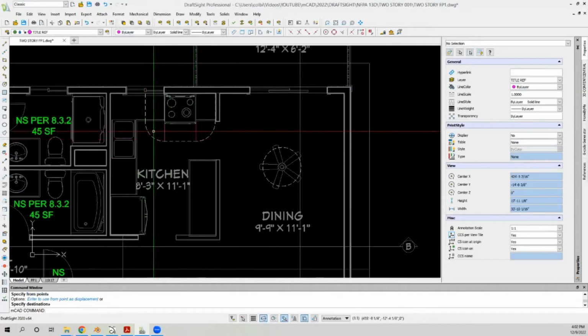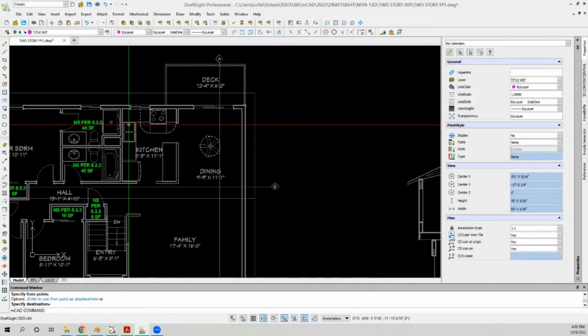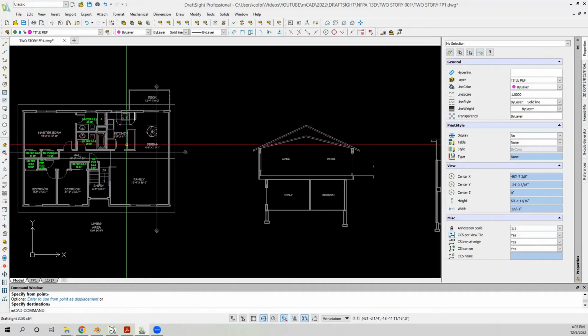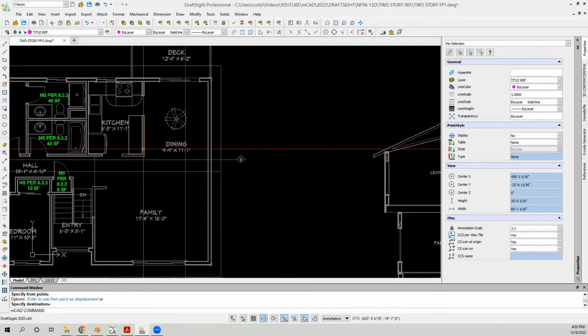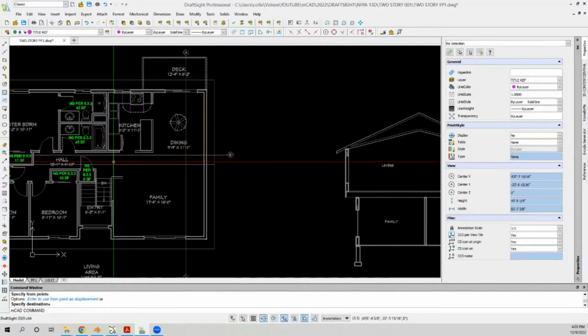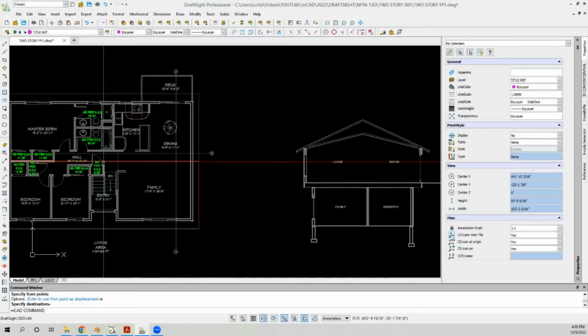Okay, so as long as we stay out of that area, we can use a regular temperature sprinkler. Now, another thing that didn't come across on here is this wall is a half height wall. And also I didn't have anything marking on there that this area is vaulted. These are scissor trusses in here. So the hallway from this line on and everywhere else in the house is a flat ceiling, but this area is sloped. In fact, I can show you real quick.